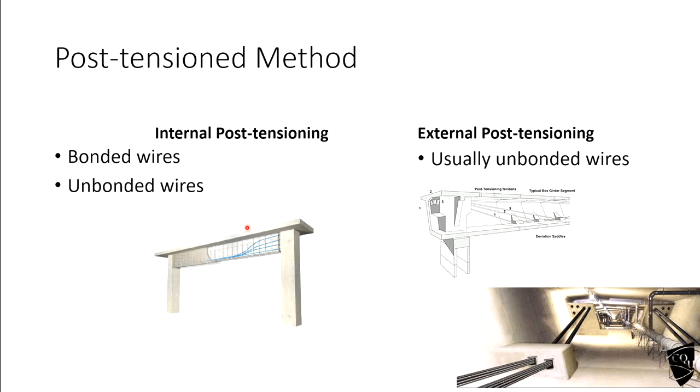You should be able to reduce the section height or size, or you should be able to use a hollow section so that the overall dead load, the self weight of the member, will be reduced. If you have a hollow section, the area will be less, or if you use a smaller cross section, the cross section area will also be reduced.